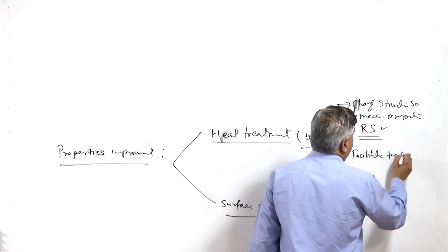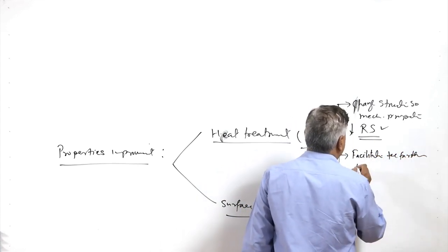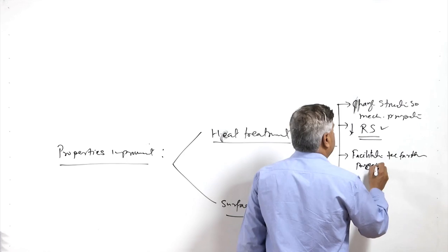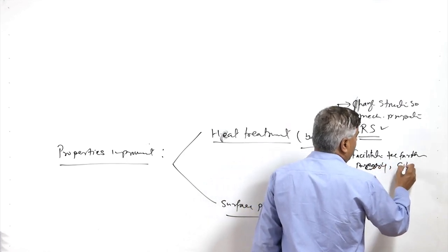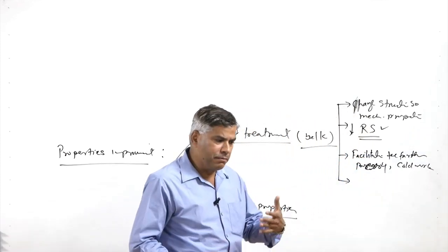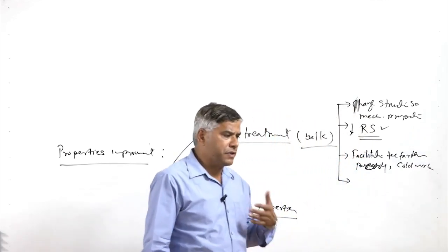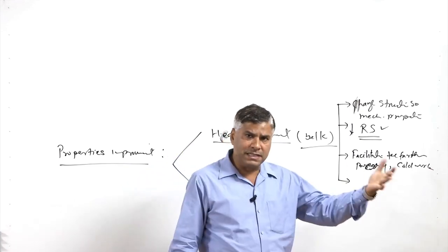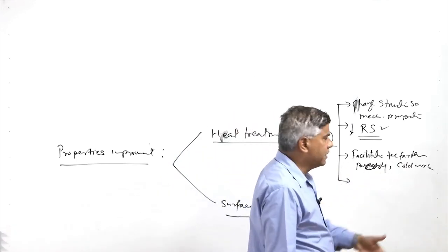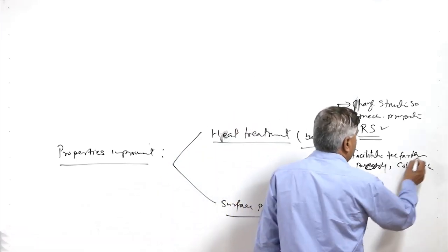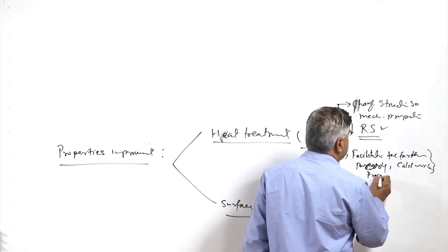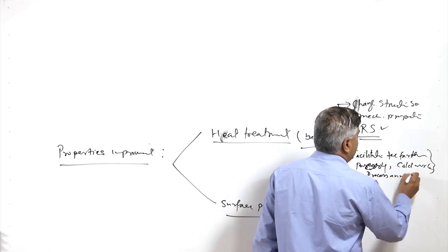the further processing of the metals, especially in the case of cold working. We know that whenever deformation based approaches are applied, the material gets strain hardened. A strain hardened material leads to an increase in strength and hardness and a reduction in ductility, which makes further mechanical working difficult. So we need to soften the material, which is done through process annealing.